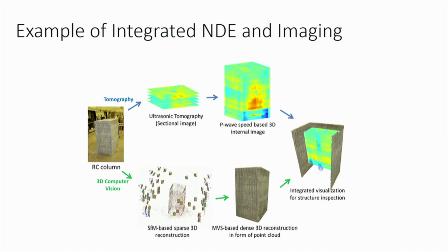And then on the other hand, we have NDE techniques. In this case, they've used ultrasonic tomography and P-wave methods to get a subsurface defect map of this concrete column. And they combined it together into this interactive digital twin, if you will, of the reinforced concrete column.